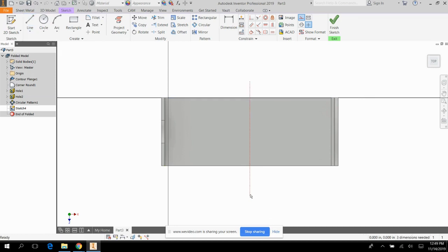And I'm going to do the same thing in the width dimension the other way. So for height up here, I'm going to find the green dot and draw the construction line through the object. And I'm going to use those construction lines to locate these center points. And so I'm going to put a center point on either side. And then I'm going to dimension those from this center construction line at 1.48 inches. Same thing this way, 1.48 inches.